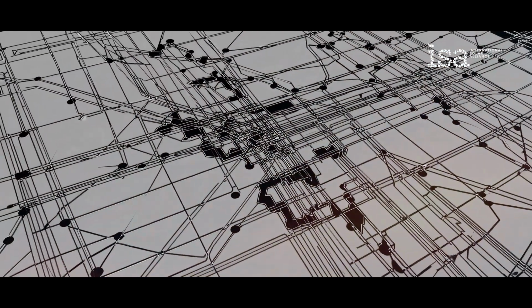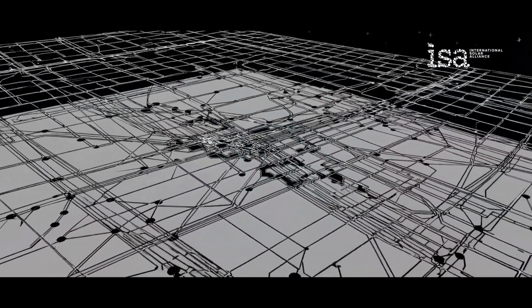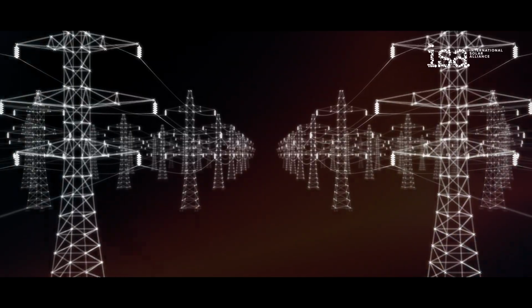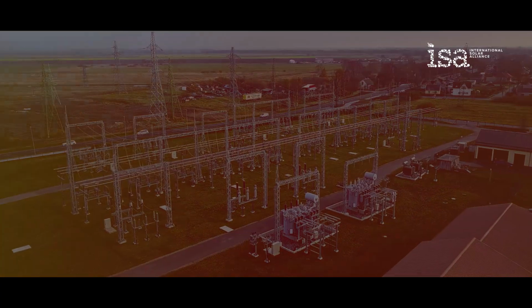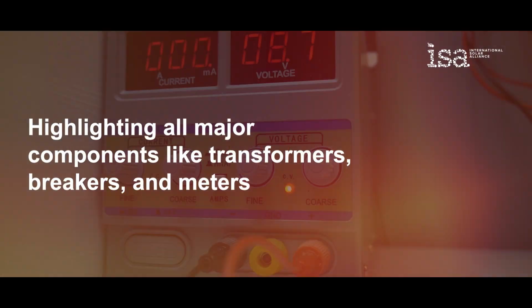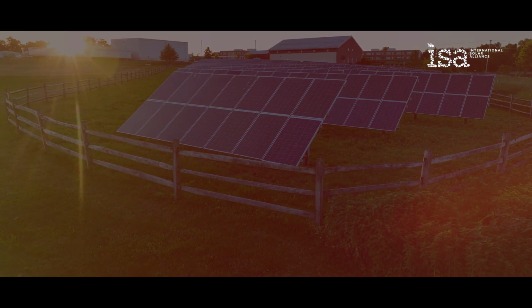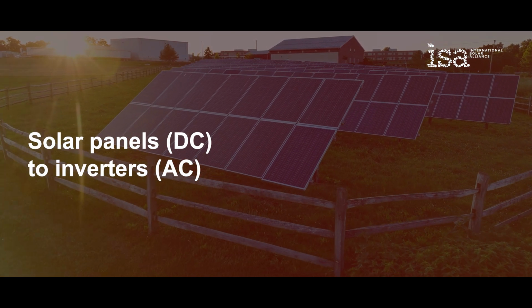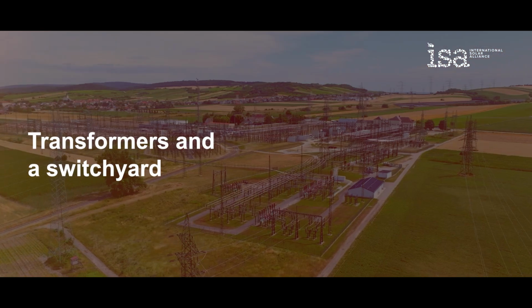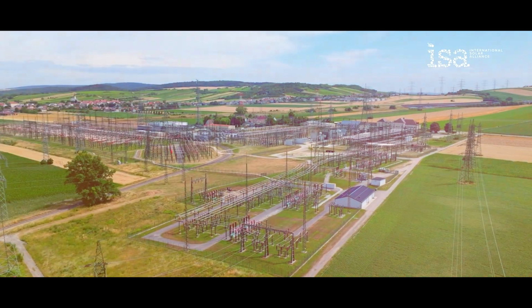A single-line diagram, or SLD, is a simplified representation of an electrical power system. It shows the flow of power from the generation source to the grid, highlighting all major components like transformers, breakers, and meters. It shows power flowing from solar panels, DC, to inverters, AC, then through transformers and a switchyard before being transmitted to the electrical grid.